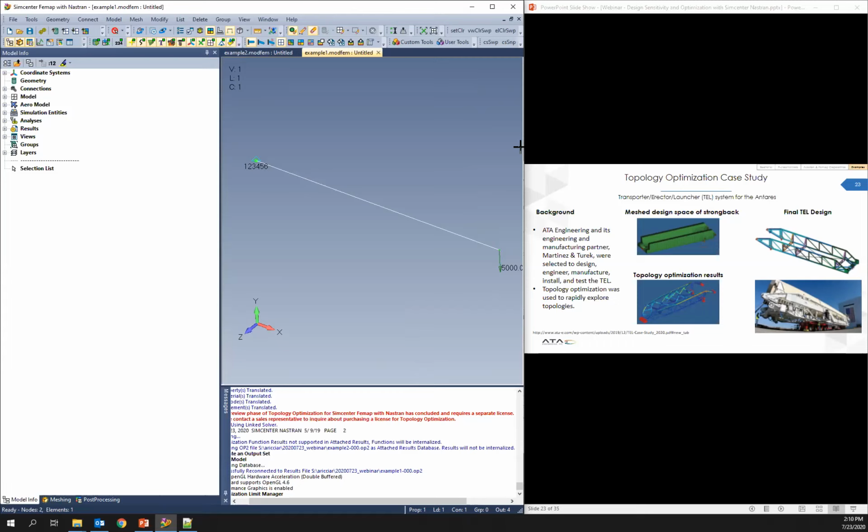There's a specific difference in that Femap chose a more convenient approach for the user with less control, where in Femap, you don't actually specify the design variable. It has a workflow where both the design variable and the design model relationship are set up at the same time, and you can't control how that's set up as much, but it's faster to set up.